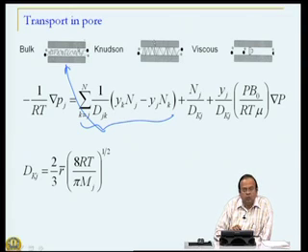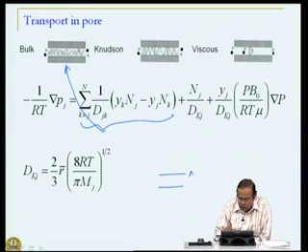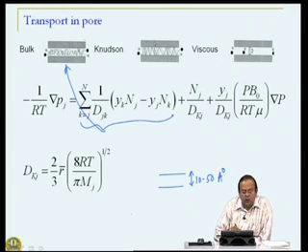But it turns out that if your pore size, for example, is of the order of 10 angstroms or 50 angstroms, then the likelihood that one gaseous molecule will interact with or hit another gaseous molecule, so molecule to molecule contact, is much smaller than that of the gaseous molecule hitting the wall of the pore.